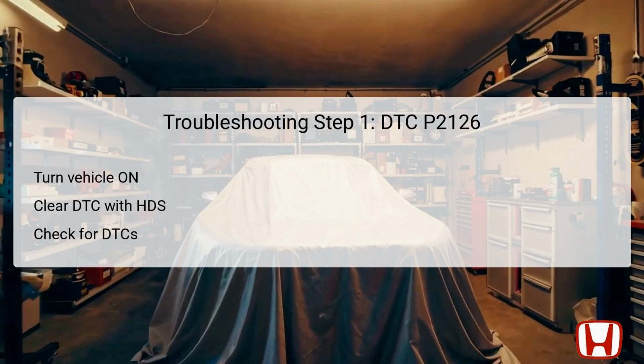Conversely, if no DTCs are present, the issue may be intermittent, necessitating further examination of connections and terminals related to the APP sensor and PCM. In the second step, the technician must turn the vehicle to the off-lock mode to ensure safety while working on the circuit.